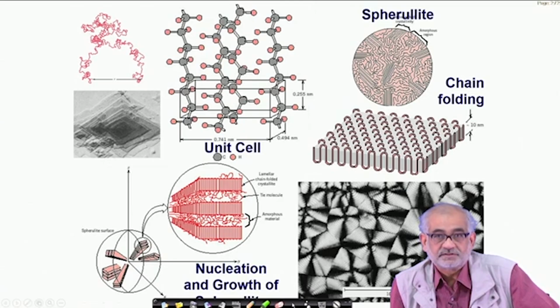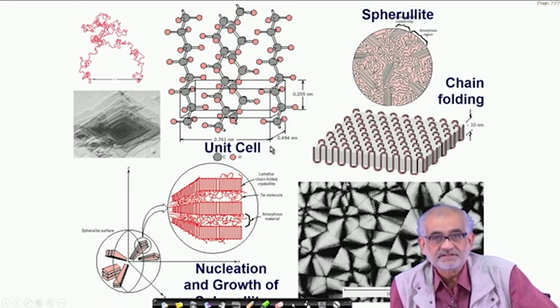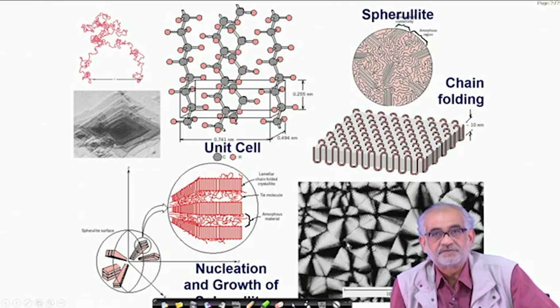So this is not, again I must repeat, going to be very easy within a minute for us to appreciate, but it's important for us to know that polymers can develop crystallinity under certain thermodynamic conditions up to about, let's say, 70, 80, even in some rare cases over 90%. But polymeric crystals are rarely 100% crystalline compared to the inorganic counterparts.